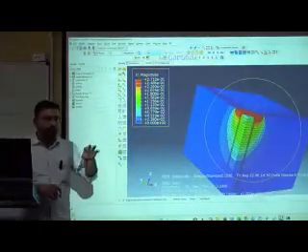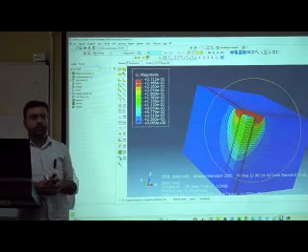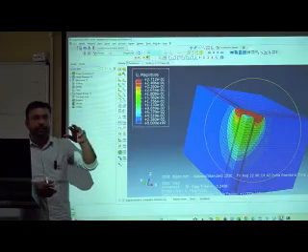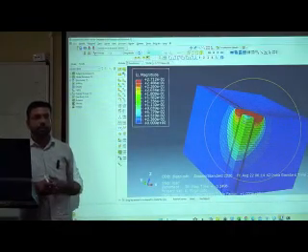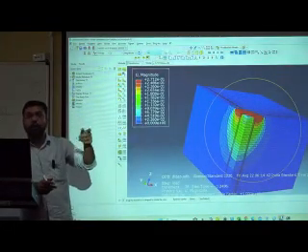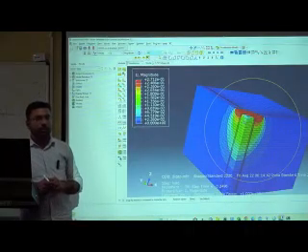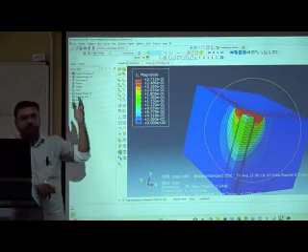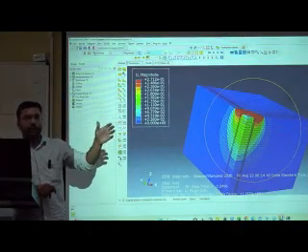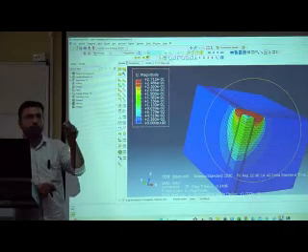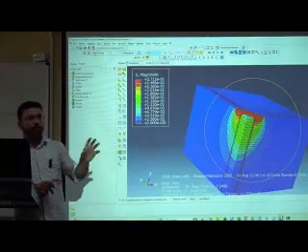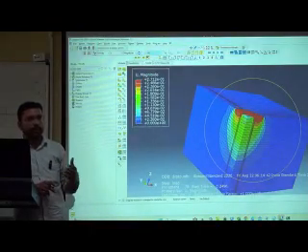so in displacement, if you go for the prescribed displacement, there is one disadvantage, that it treats the raft as rigid. It will not show the differential settlement of the raft. So differential settlement is a very important part. So if you apply the load as pressure on the raft, then only it will show the differential settlement. Okay, the second point is you cannot find the bending moment of the raft, this pile, if you go for the solid. If you want to find the bending moment of the raft, then you have to choose the shell instead of the solid. Okay, so keep this in your mind while simulating this part.